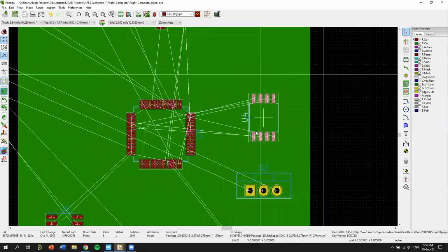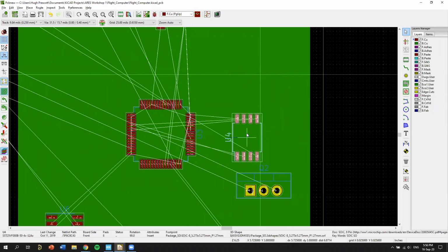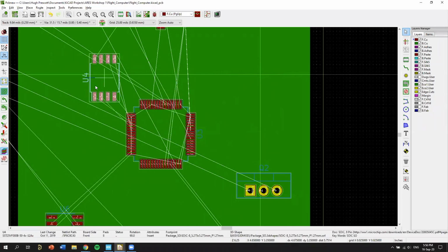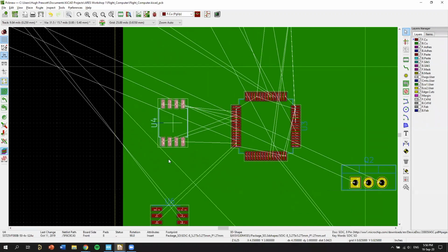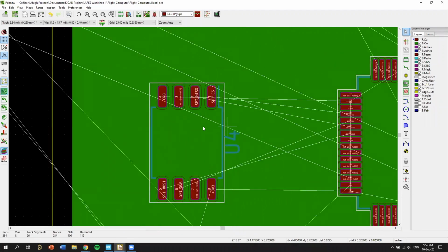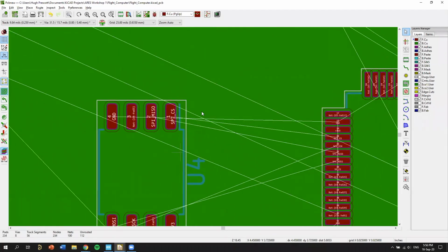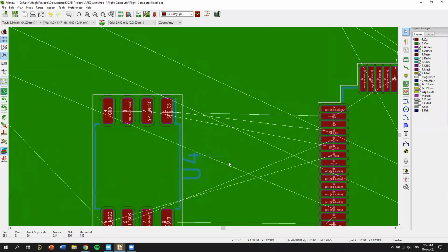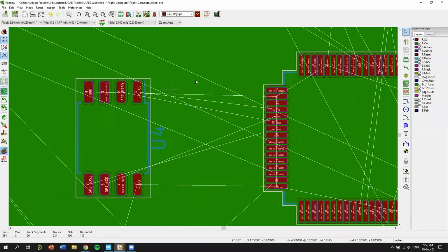So for example, I just move it around and see, all right, all of these connections actually want to connect on this side. You can press R to rotate things. Actually, this is our SPI chip. Now, what you can do is hold Shift X. That brings up our routing tool.